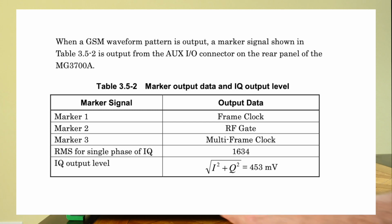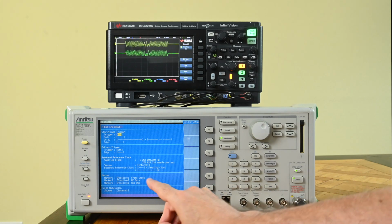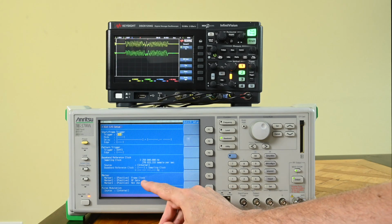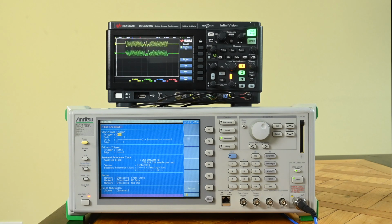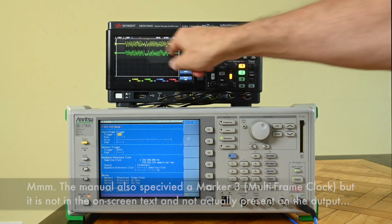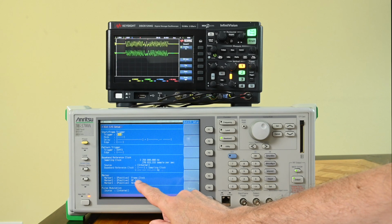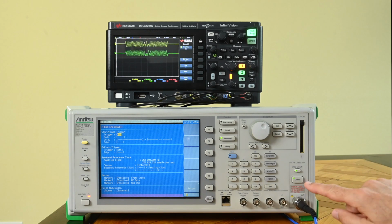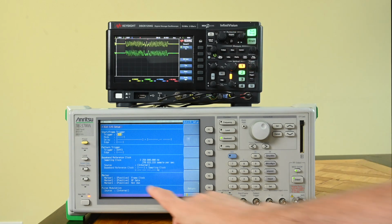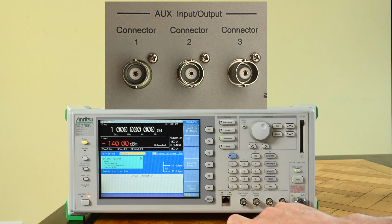It's very extensive, but even easier, I can go to the external IQ setup menu, and I actually see here there's a marker 1 equal to the frame clock and a marker 2 equal to RF gate. Frame clock, basically, is apparently linked to the frame that GSM is sending out. RF gate is apparently linked to the whole RF modulator being turned on and off for this particular signal. So they actually turn off the RF signal in this particular example. So we can take these outputs, they're on the back of the device on BNC connectors.